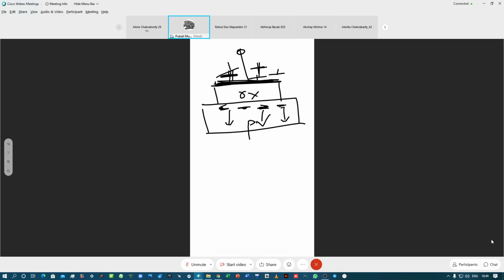Now if this positive charge is still larger, we will see what happens in case 2, case 3. So case 1 was accumulation, case 2 was as if an induced space charge region, where you have negative charge accumulating on the p-type substrate, at the boundary of the oxide and the p-type substrate.